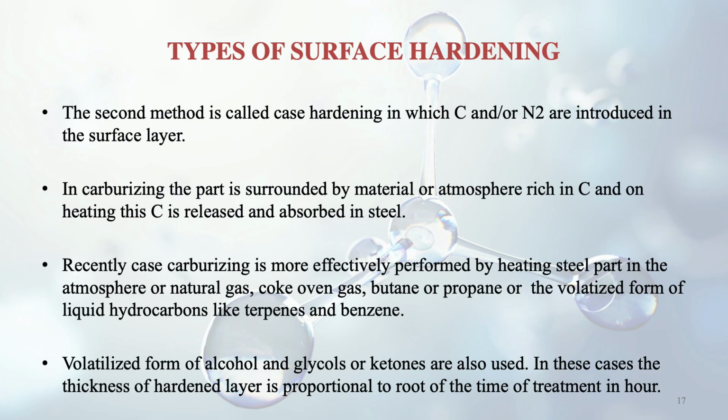In these cases, the thickness of the hardened layer is proportional to the root of the time of treatment in hours. So the thickness of this hardened layer on the specimen is directly proportional, it is said, to the root of the time. So it will be dependent on the time of treatment. So time of treatment will be very important in this case.